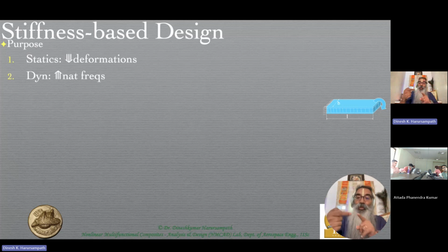But the actual mechanism by which this happens, both the control system and eventually the aerodynamic coupling between the pitch and the flap, is very, very interesting. Since this is the situation, you can easily see that if there is a coupling between the natural frequency of the blade and the dynamic loading frequency coming from the aerodynamics, because of these changes in pitch, then if they're close to each other, resonance can occur either on ground or in the air, and that could be quite disastrous.